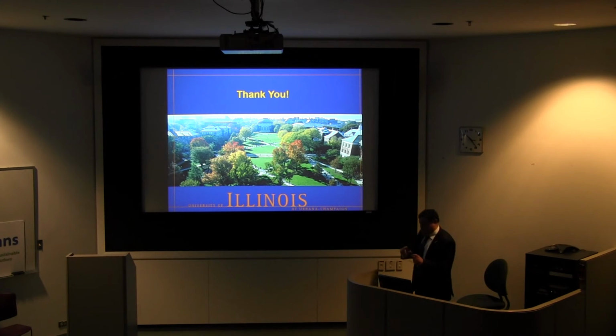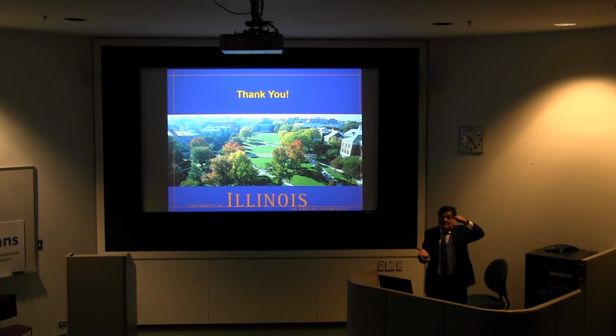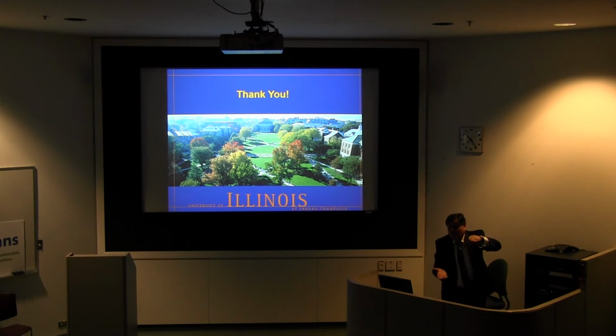In GPR, what you're going to see is the pulse that interacts with the surface, okay? And from the time that you send it, this one here will show you that there is an increase between the time that you send the signal and when it hits the surface. So you can see an increase now in that distance. Let's say that you decide to go with 1.5 feet, now it's 1.6, you will be able to see that. Now, for the asphalt concrete, at the minute that it hits the asphalt concrete, that's when you start. So if the thickness remaining is an inch, you will be able to see that 1 inch. So does that answer your question?